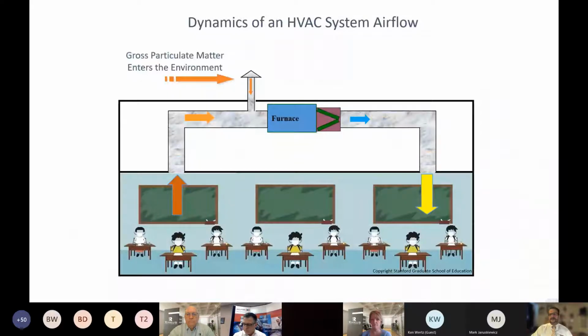Now, in the classrooms or environments inside the school that have either a recirculating system or a furnace, generally the mechanical systems have filtration inside them that can be upgraded. When the filtration is pulling back air from the room and filtering it through the furnace itself, a higher level of filtration will pick up more particles in the environment. These systems are designed to run around if the fan is left in the on position on the furnace, which is not a normal thing for furnaces or air conditioning systems to have. But there's a little switch that allows furnaces to be run in a continuous fashion.